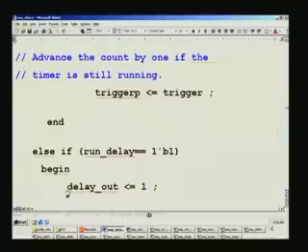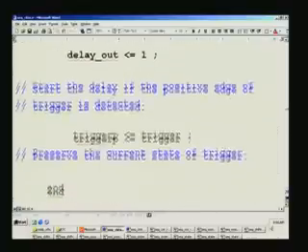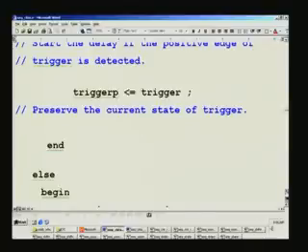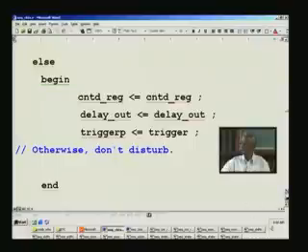And mind you, in all the always positive edge clock blocks, whatever signal that you put, they are all automatically registers. That is why once you have set the value, it will remain for a long time, indefinite time, till you veto it, right. So otherwise just preserve here, and just preserving that.